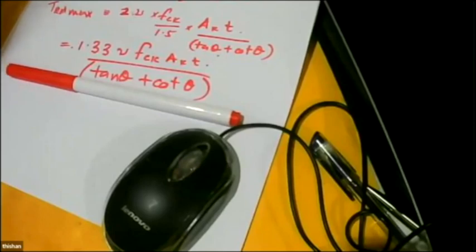Now, if you are an expert engineer, you should train your eye. The moment you see a situation like a secondary beam system in two different directions, then it's not a problem. You can just analyze it without worrying about torsion. Anyway, when we are analyzing secondary beams, we introduce pin ends, pin supports, where the secondary beam is connected to the main beam.